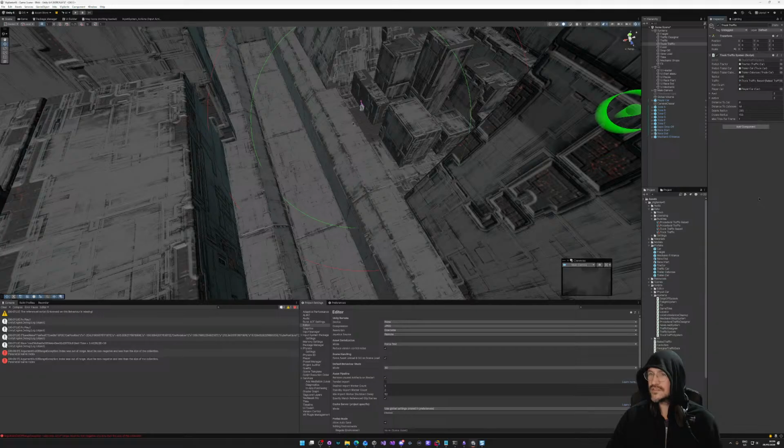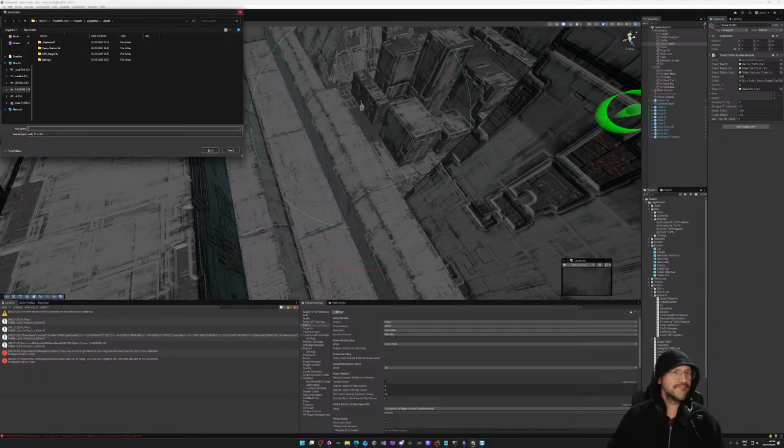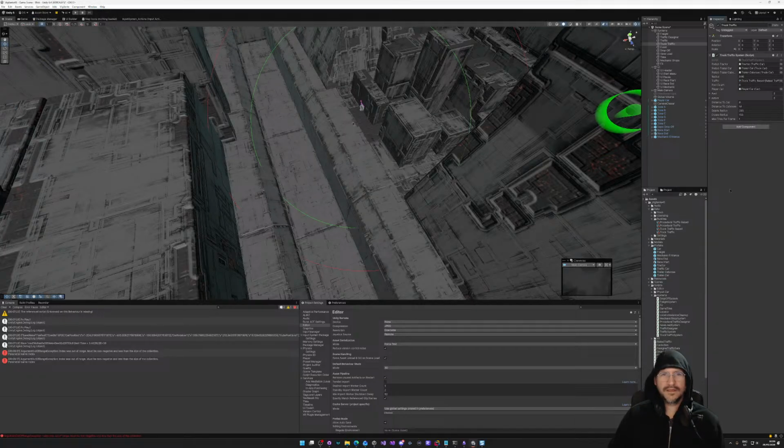Tries per frame: one. And also the radius of where I can create them. I should expand this one because there's much less that's going to be inside of this one. Okay, let's do that. So one per frame, and we're going to widen up the radius to say 800 and set the create radius to 600. Cool.